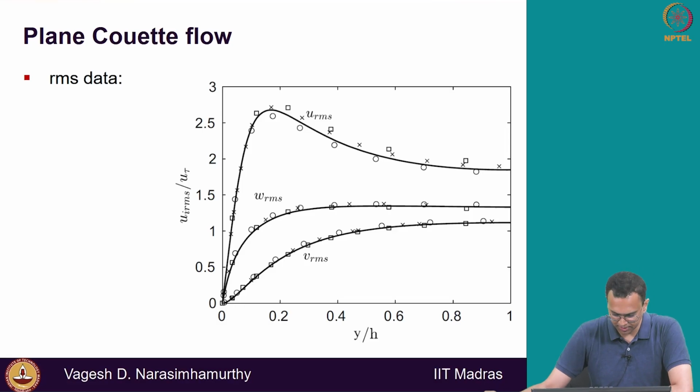Okay, so let's get started. You have all seen this graph before where I showed you the RMS data for wall bounded turbulent flows, and we have discussed that there is something called anisotropy. Even in a flow like a turbulent plane Couette flow or any other turbulent boundary layer, you will get this URMS, VRMS, WRMS of different values, not orders of magnitude, but like twice or thrice of that one, but they are of the same order of magnitude that we discussed. And y is the wall normal direction.